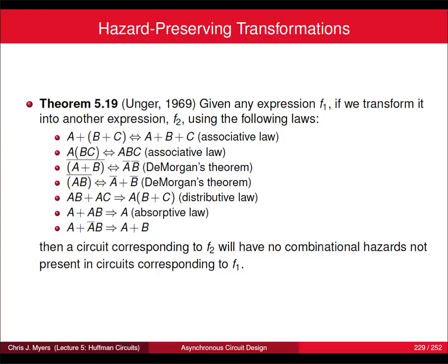So when we made something hazard-free, what did we tend to add to the circuit? More states? Not more states. More encoding bits for states? No, I'm talking about hazard-free logic synthesis. Were our covers as small as they were for conventional synchronous design? Or did we have to add prime implicants, or even non-prime implicants to get to a hazard-free cover? So those, to a simplifier, are going to look redundant.